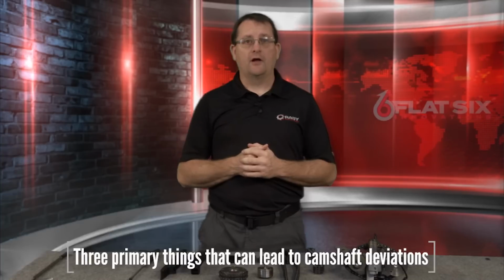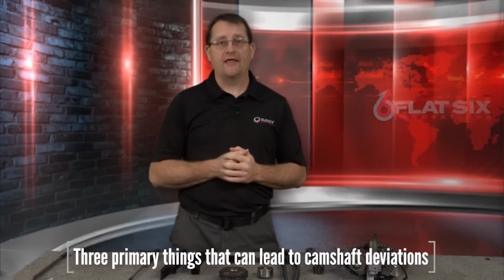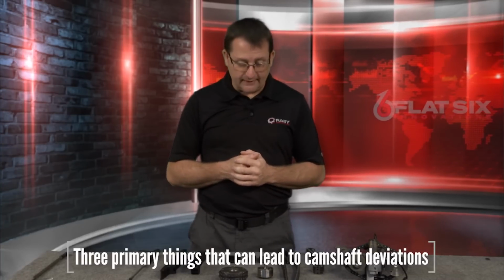So if you have that 3-chain engine, your car is a 2002 996 or 997 variant, or it's a later Boxster Cayman from 2003 and on, then you're going to end up having the 3-chain engine. And there's only 3 things that are responsible for wear in a 3-chain engine that are of note. And basically, that one is going to be a worn IMS bearing.